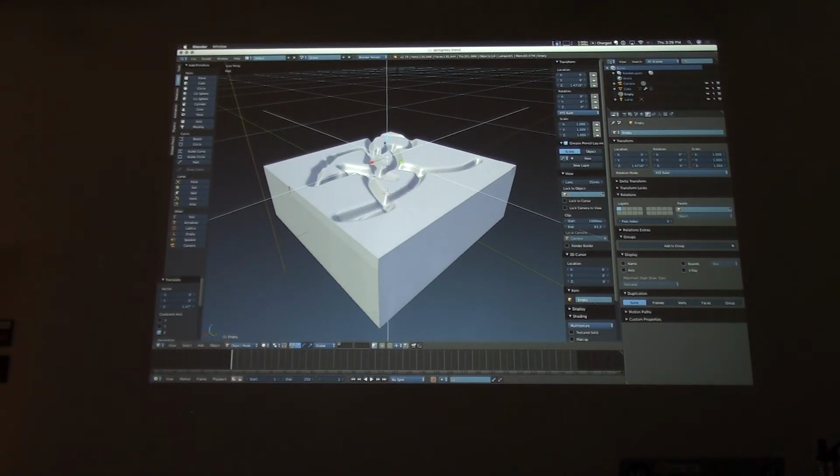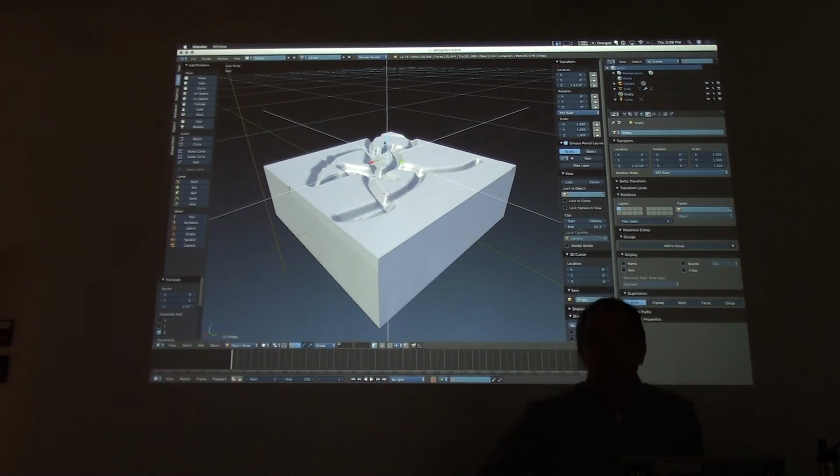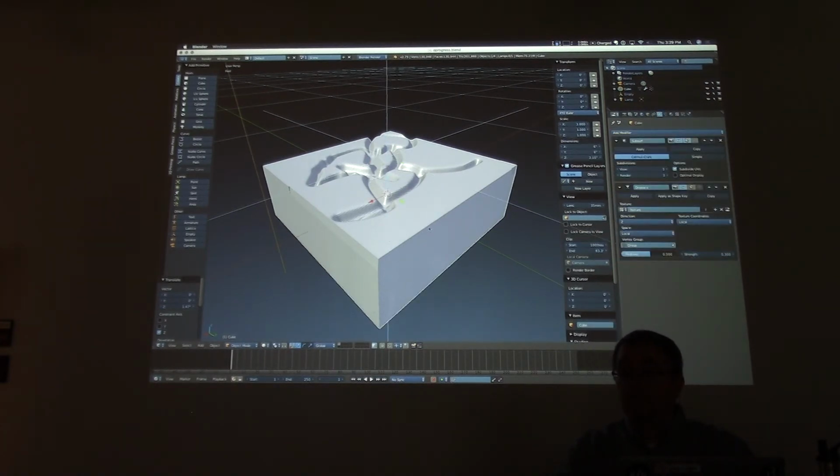So how do I move the axis? Just grab the blue arrowhead. Oh, cool. All right, so we have our empty. Everybody has their empty? All right. So now we need to assign the empty to our displacement texture. So I need to click the cube because this is a modifier on the cube. Otherwise I'm not going to see the modifier.